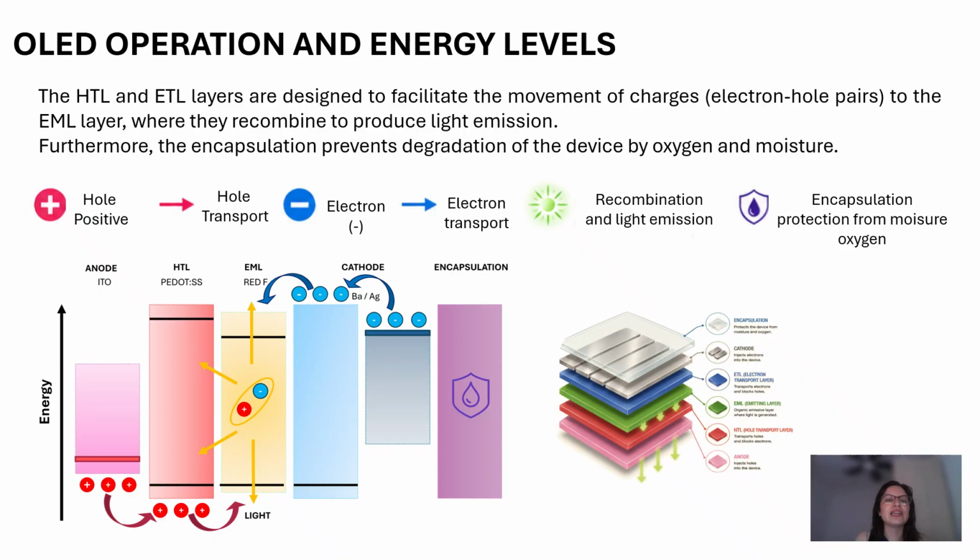Now, in these materials, the cathode injects electrons into the LUMO level. The anode pulls electrons from the HOMO level, and here is the moment when the holes are created. Charges travel to the emission zone and they jump from molecule to molecule. The electrons and holes are found in the emitter shell. They form a neutral state called an exciton, and finally the electron falls from the LUMO level to the HOMO level. This loss of energy releases a photon of light.